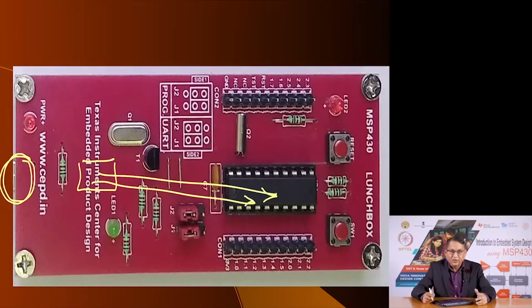Now, it turns out that there are two UART ports, so to say. One is a conventional UART port, that is a serial communication port, and the other is the port to be used when you want to use the USB to download a program through the bootstrap loader from the PC into the memory of this microcontroller.